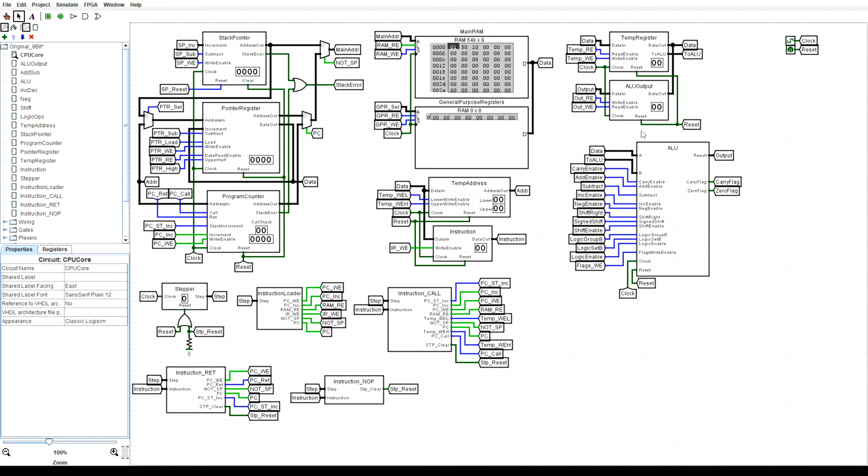Let me interrupt with a little bit of post-commentary. The multiply instruction will be present in the final design, but the divide instruction will not. I've also updated the instruction listing that you've seen so far. Back to non-post-commentary. So we can do multiplication and division, and then have another instruction for transferring whatever's in the upper half of the result to the output register. Post-commentary again, just to be clear, regardless of what you hear in the sections that are not post-commentary, there will not be a divide operation. There will, however, be a register to separate the lower and upper half of the multiply operation. Back to the video that I've now interrupted twice.